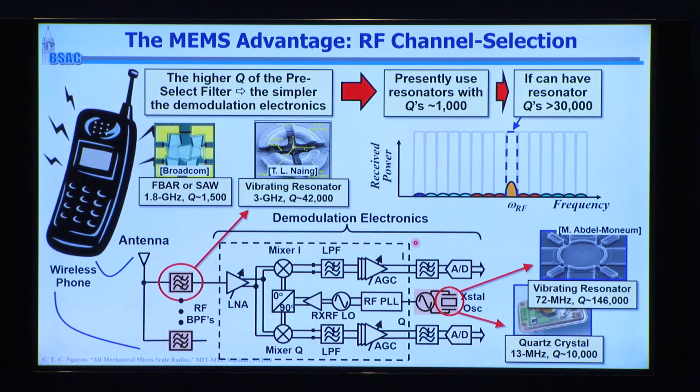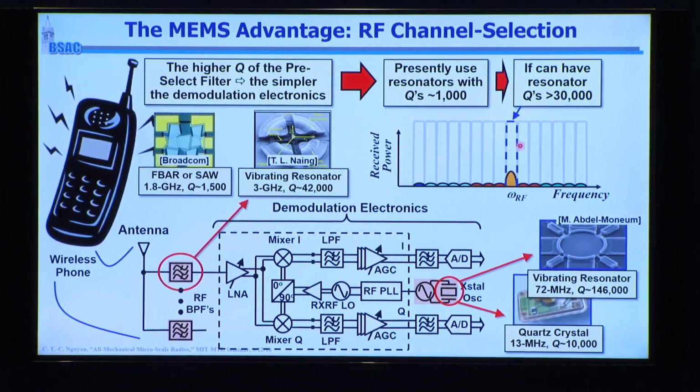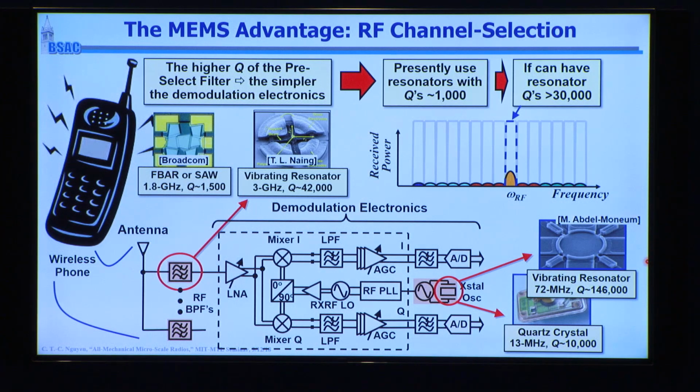All right, so going back to this. So we have this technology now. We don't have it at the gigahertz frequencies yet. So there's still work to be done to do that. But if we get that, this can work for a VHF type of communication capability as well. Now we could take this whole thing and, instead of having maybe a single filter, maybe have several filters or tune them over a certain range. So I should say these are not widely tunable. The higher the Q of your technology, the lower your tuning range usually, although that's starting to change. So at upcoming conferences, you'll see both high Q and large tuning range. But at least if you can't tune, what you'll do is just build many filters and tune that channel across whatever range you need it to be.